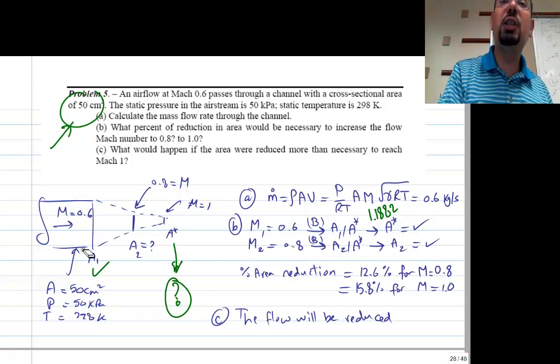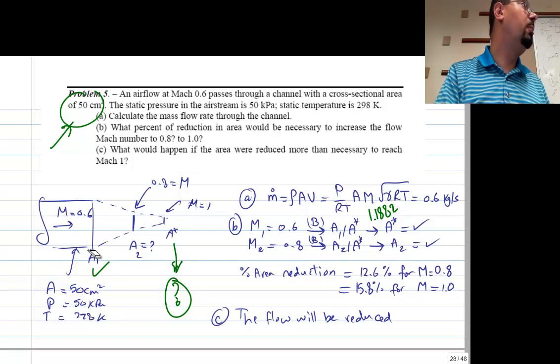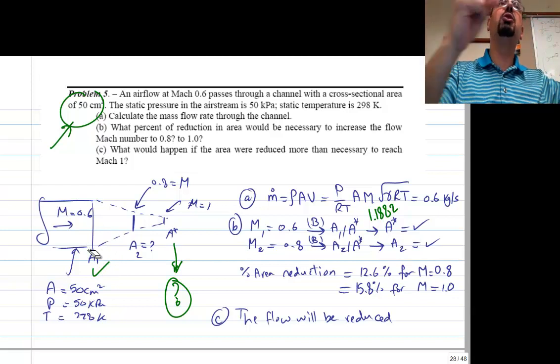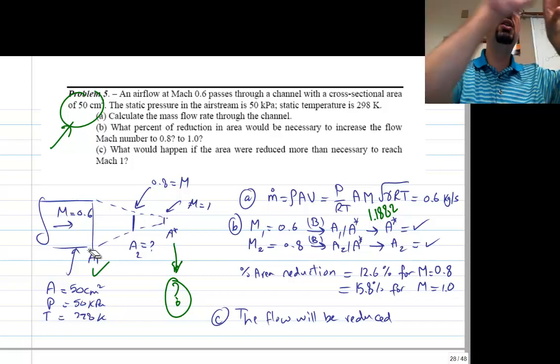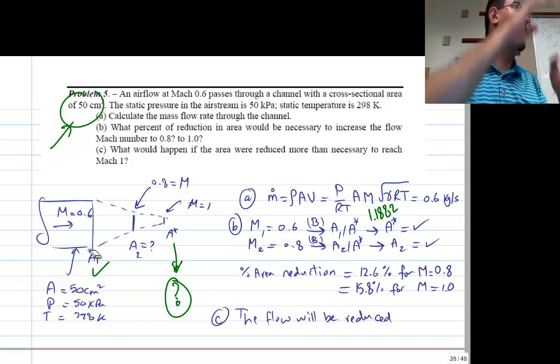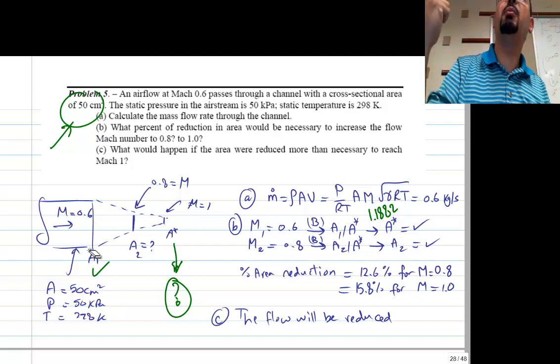So it's the same thing for this pipe when I'm asking about A star. Where is it? It's not in that drawing. But at that Mach number, and you have this ratio, we promise you if you take this area and you reduce this duct to this new area star, you will hit Mach 1. Just like when you take that flow, that Mach number at that static pressure, and you slow it isentropically, you hit P naught. It's the same thing.